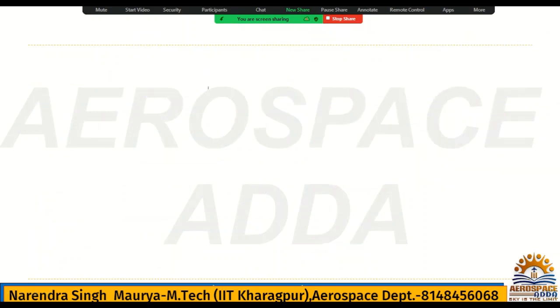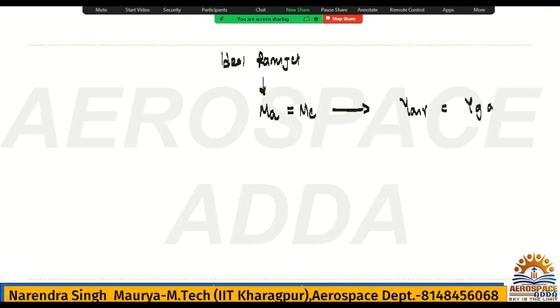What I said for ideal RAMJET, listen carefully, okay? Ideal RAMJET, I had said MA is equal to ME. So this condition was very special, when gamma of air is equal to gamma of gas, when R of air is equal to R of gas.